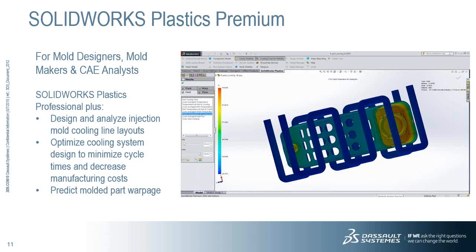This also lets you design and analyze injection mold cooling line layouts. As you see in the picture, these are the layouts built for cooling, and you can also see the impact of how good my cooling is or how bad my cooling is, what is the effect of the cooling layouts I have designed, so that I optimize the cooling layout so that cooling is adequate inside the mold.